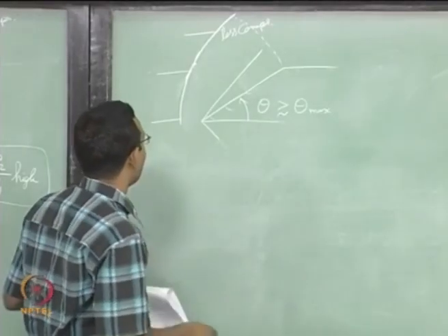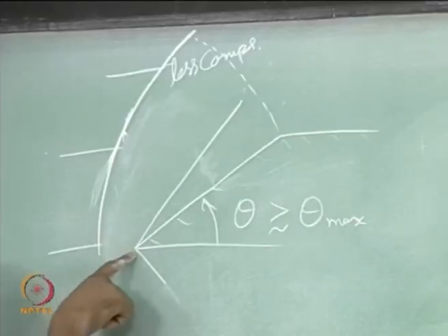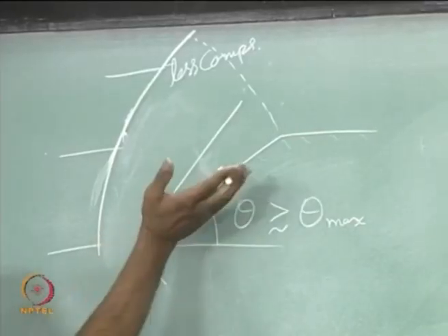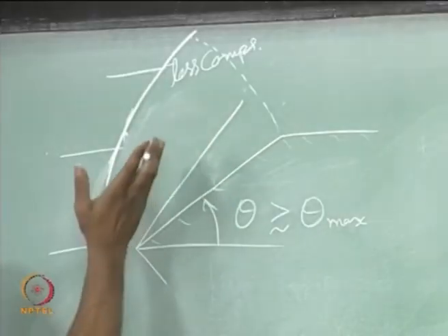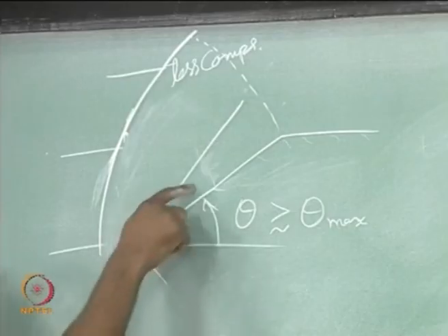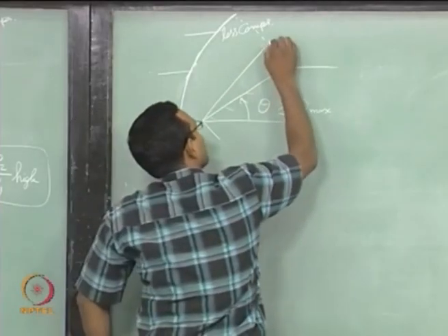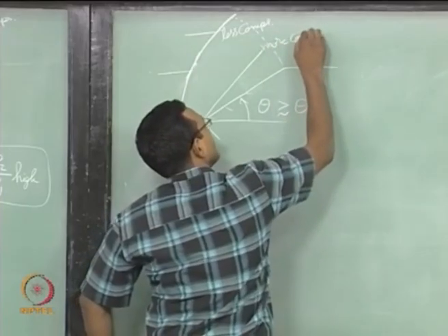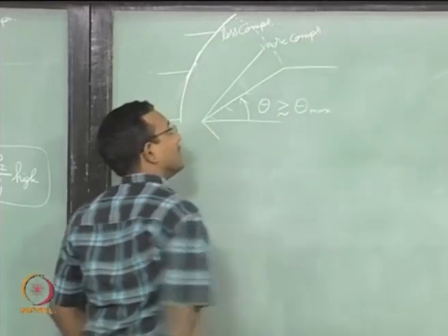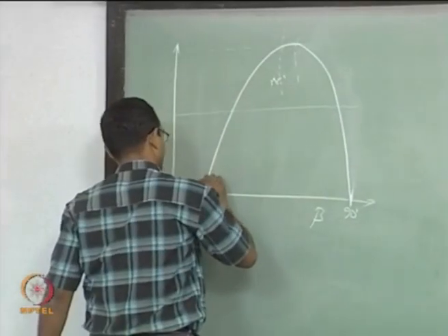So, overall what is happening, it is now an attached shock. For this to get detached now, I have to increase my angle much higher, so that it will go and sit outside. Right. This is not the critical angle for this particular Mach number, if the gas is more compressible. That is what we are seeing here. Now, we will go back to that and we will probably have to stop with this.